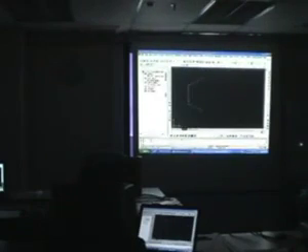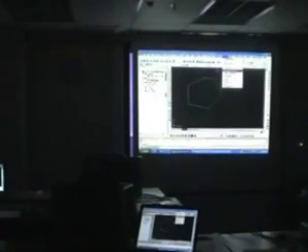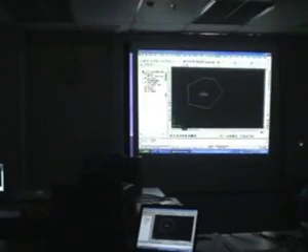I'm going to draw just a non-polyline here and say, okay, let's say for example we want to use this as a parcel. I'm just going to define it from a polyline and just pick the line. You can see how the parcel number with the area appears automatically.